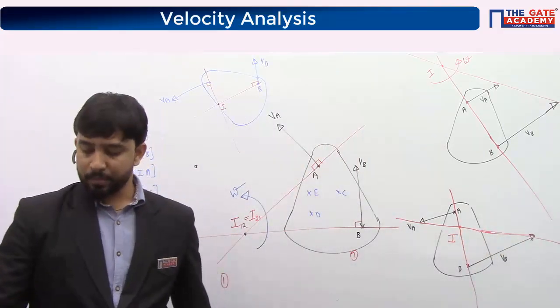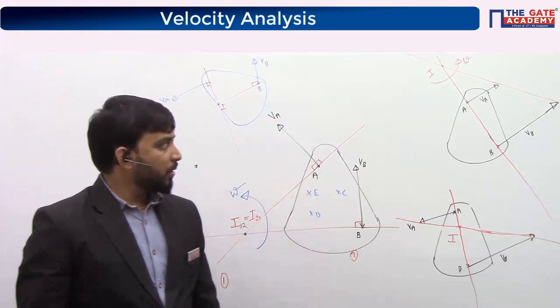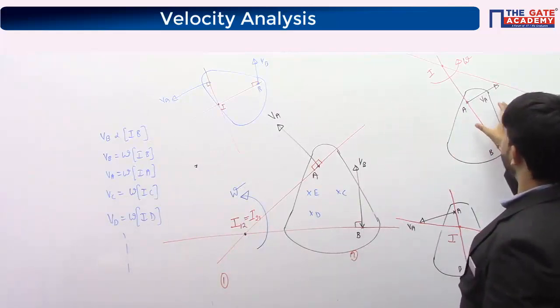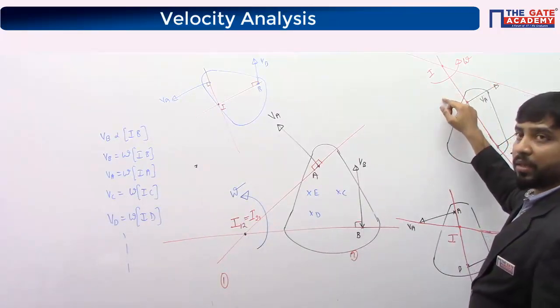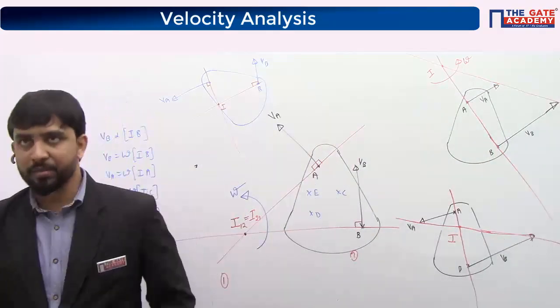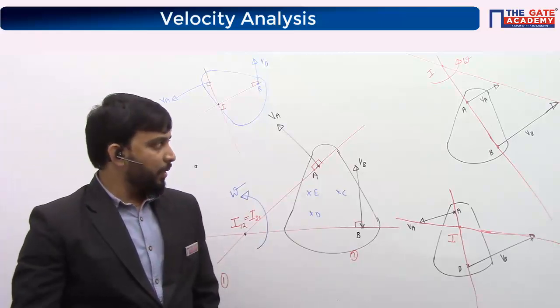This is I-center. So if two velocity vectors are parallel, you may encounter a case like this. Here in this case, if the two velocity vectors are of same length, then these two lines will never intersect, okay? So we say I-center lies at infinity. It's in pure translation.